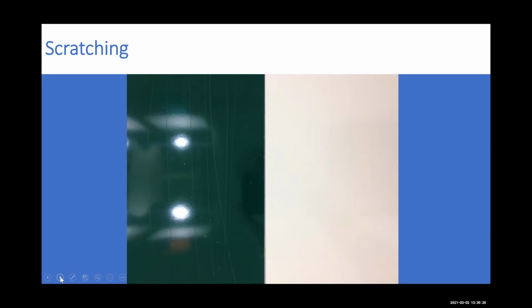have been scratched equally using a box cutter. The scratches on the darker color are more visible than the scratches made on the white. This is because the decorative paper that gives you the color, the pattern, is impregnated with a melamine resin. And when the melamine resin is scratched, it fractures and it turns white. So therefore, it's obviously less noticeable on the white HPL because it matches the decor.